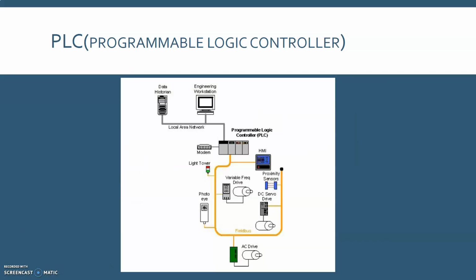Now let's look at the second thing, that is PLC, programmable logic controller. So PLCs are used in both SCADA and DCS systems as a control component of an overall hierarchical system to provide local management of processes through feedback control as described in the section above. In the area of SCADA systems, they may provide the same functionality as an RTU. When used in a DCS, PLCs are implemented as local controllers within a supervisory control scheme.